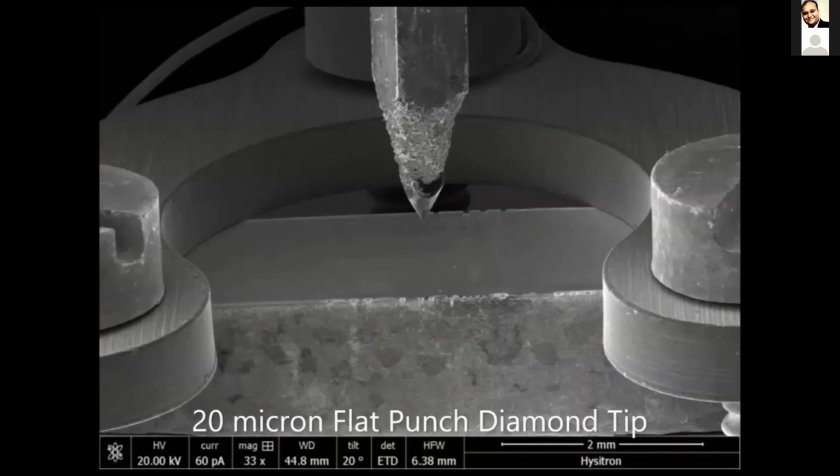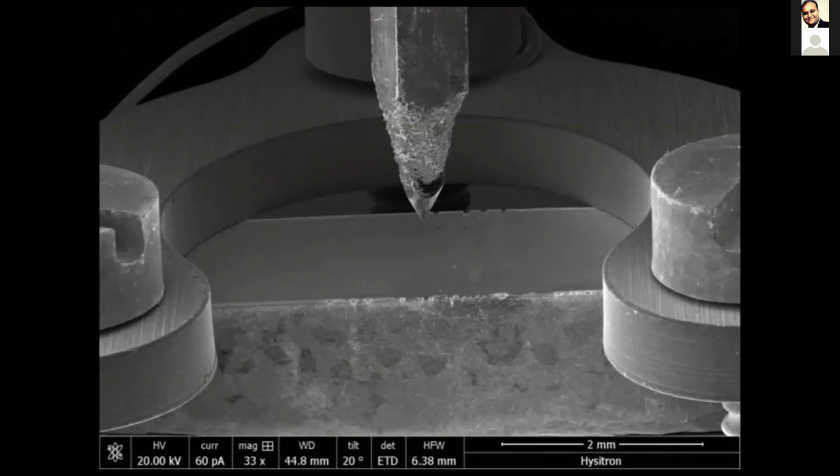And here's a low mag SEM image of the sample, the horseshoe clamp, and the tip together. You can see how the viewing angle works with the opening at the top of the horseshoe clamp, allowing you unobstructed visibility of your sample area. Those little black dots are locations for pillars. And then you can see how the tip comes in from above in order to compress your pillar of choice.